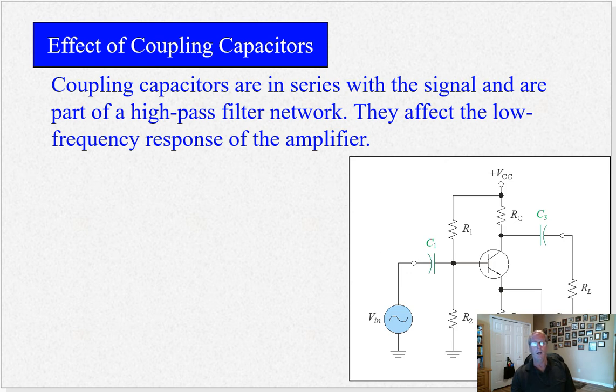In the meantime, we are going to be going over the formulas, and there's a few examples in this presentation here. As I said, these coupling capacitors are in series with the circuit, so C1 and C3 are coupling capacitors. Anything in parallel is called a shunt or bypass capacitor, so in this case, C2 is a bypass capacitor. The coupling capacitors are in series, and that forms a high pass situation, right? Any capacitor shorts out to high frequencies, so that basically, quote unquote, improves the series connection here. So at higher frequencies, C1 is going to be a lower impedance, as is C3.